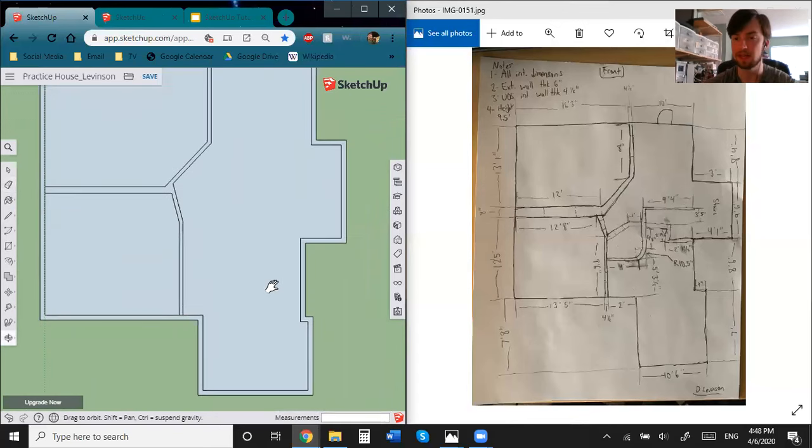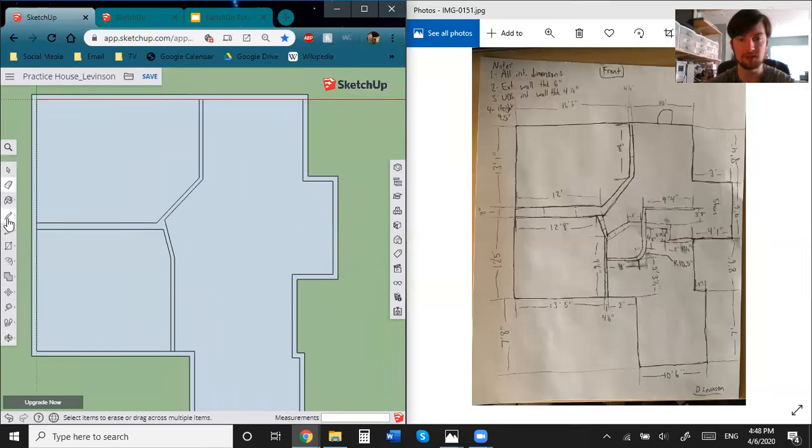Now we have the kitchen. So let's get going drawing, just keep going drawing more lines. And we have a bit of a challenge here because we have actually an arc in the kitchen. There's an arc, but that's going to be okay. So we'll go from this endpoint right here, and we'll go upward. It says right here, 5 feet, 3.5 inches. So we'll go up 5 feet, 3, and for the sake of practice, you can do 3 space 1/2 and press enter.